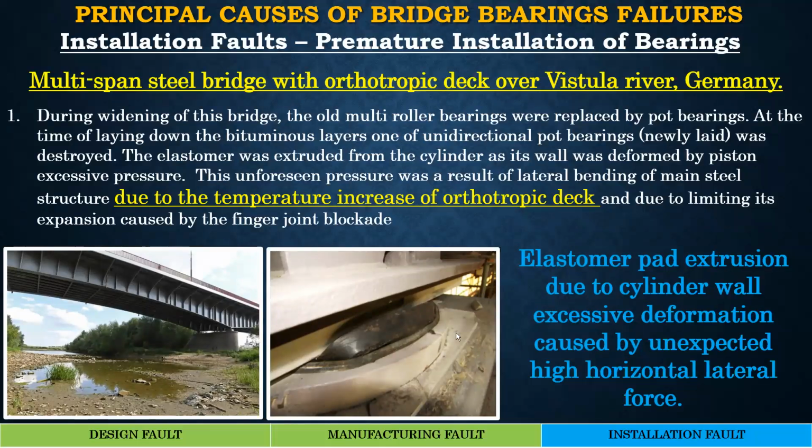This is another failure of the elastomer. I think I have shown this slide earlier also. This is an elastomeric pad extrusion due to excessive deformation caused by high horizontal lateral load during construction. As I mentioned, during construction, if you do not release the forces properly, and if it causes very high forces, then it can cause collapse of the bearing.